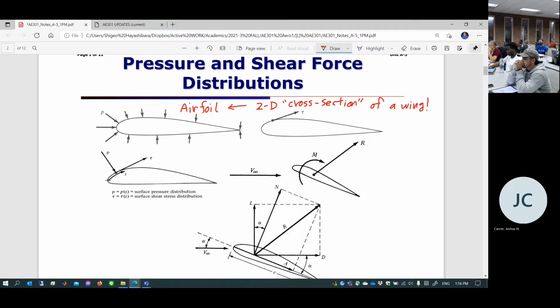We only take a look at pressure measurement. That is what the wind tunnel test is all about. You're going to put pressure taps in to get the pressure information, but you can never measure this kind of thing, so we purposely ignore that. So low-speed wind tunnel testing of pressure measurement essentially has this implicit assumption. Okay? But theoretically, we can, of course, include the shear stress distribution over a surface. We are going to do that for a moment, because this is theory.